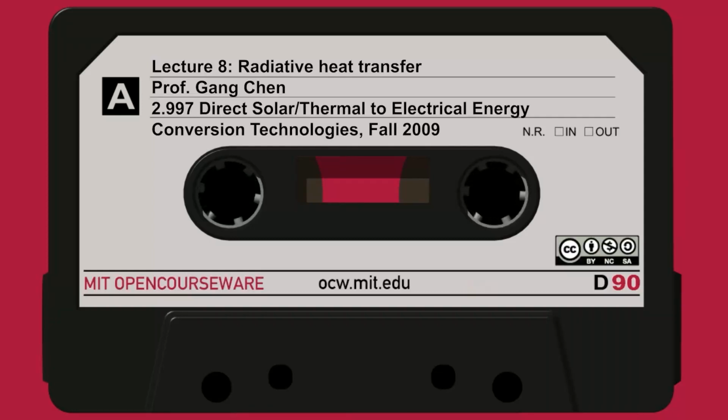Because A_S F_SE equals A_E F_ES, when I normalize per unit area using the reciprocity, I will write this as the Sun's emissive power times the Earth-to-Sun view factor. Oops, I forgot this number.